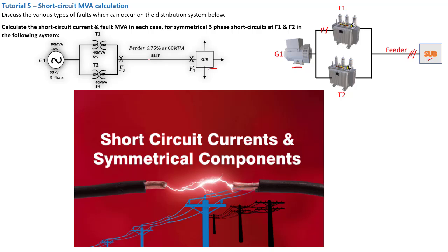And we can also get a short circuit in the transformer. The other fault we can get is a short circuit inside the transformer winding. Like T1 and T2 here, they've got a primary and secondary winding. So you can get those two windings short circuited, and that can also create a fault. So that is fault number 2. What else can we get? Now we've got a feeder. A feeder is a transmission line. Anything can happen. Your pylons can fall, or your cables can short, and all sorts of things can happen. You can get a feeder fault of that nature.